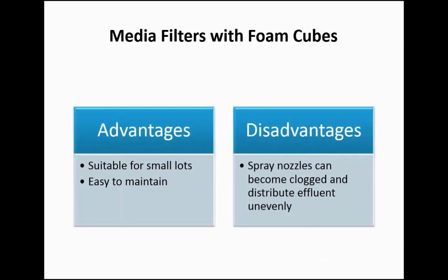These are the advantages and disadvantages. Basically, they are applicable to small lots, and it's easy to maintain. However, spray nozzles tend to become clogged, which will distribute the effluent unevenly.